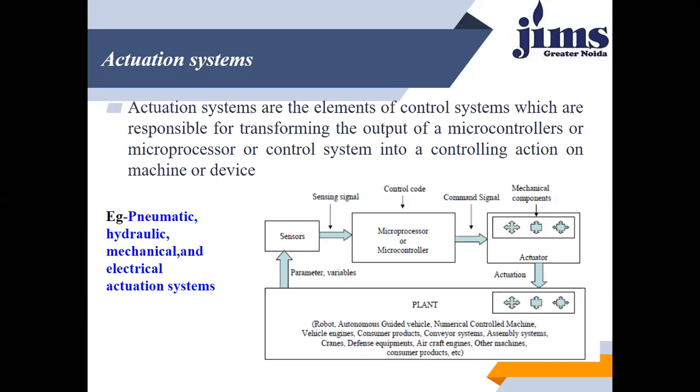Let us suppose you are looking at work that is not heavy. Then of course you would choose pneumatic actuators. Why? Because they are leakage free, a neat and clean source of energy, and compressed air is available in plenty in the atmosphere without paying much cost. So somewhere the hydraulic actuator is far better than the pneumatic actuator, and somewhere the pneumatic actuator is far better than the hydraulic actuator.